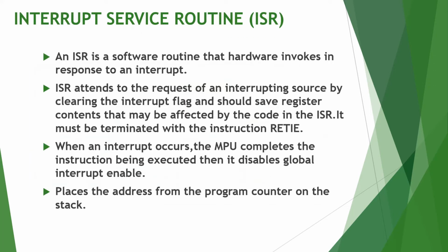Then comes the interrupt service routine. An ISR is a software routine that hardware invokes in response to an interrupt. The ISR attends to the request of an interrupting source by clearing the interrupt flag, and should save register contents that may be affected by the code in the ISR.